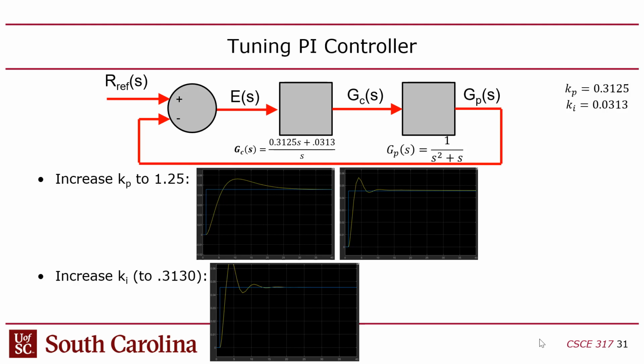But I just threw caution to the wind and said, look, I'm just going to try stuff. So I increased the proportional response to get it up to the set point faster. And that worked pretty well, actually, because the overshoot is about the same as it was.